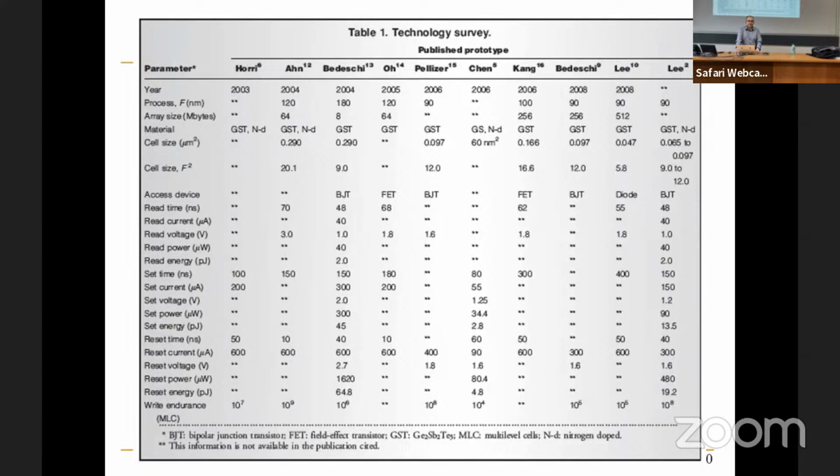There are different reasons for that. Sometimes your cell is not dead, but it's not reliable. Then that means in order to avoid errors, you need a much more powerful ECC, and that's going to cause a lot of issues. But there are also some memories that after this endurance are completely dead. For example, they are stuck at 0, so every time you access it, you will only read 0.